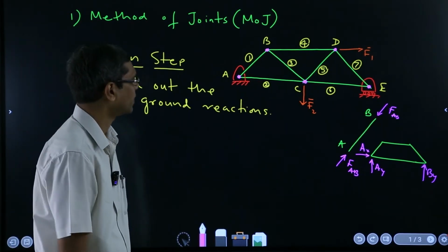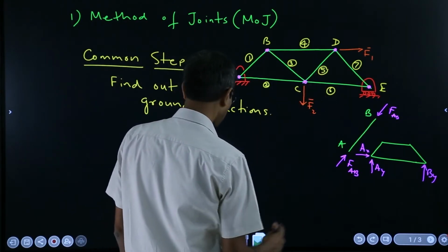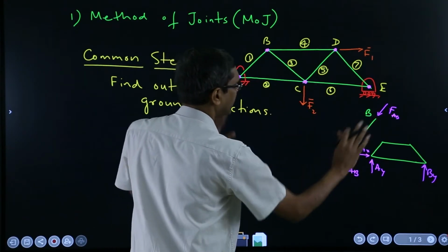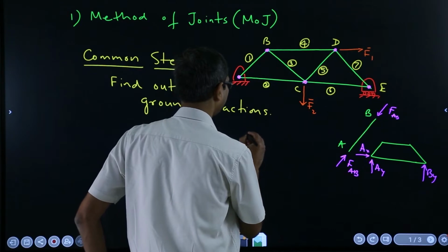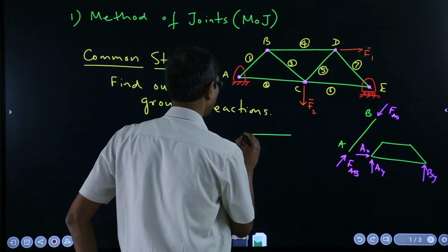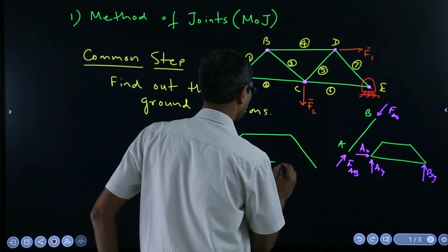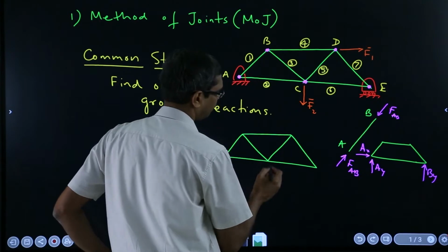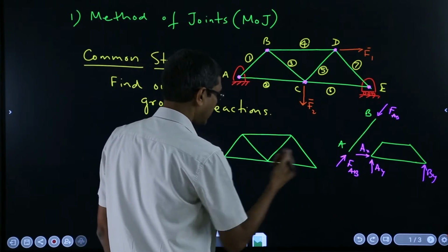It is common for both. And then what you should do is you should represent this truss without showing any of the supports whatsoever, just show the forces that are coming. Maybe there are external forces or internal, the reaction forces.